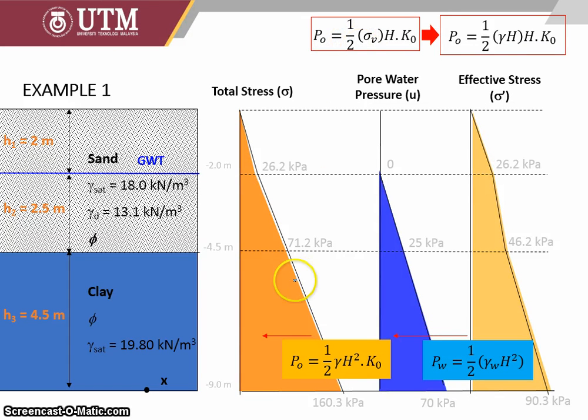When we already have the vertical stress, for each level of soil in the stress diagram, we can define their own pressure. So we can have a pressure here, another pressure here, and also pressure in the third level. But ultimately, we can combine all the total pressure, and for the Rankine method, later on we will see the Rankine method in active and passive condition.